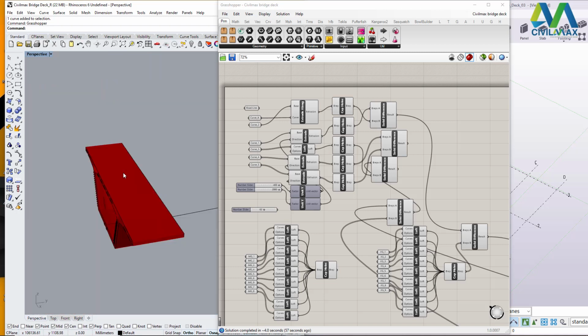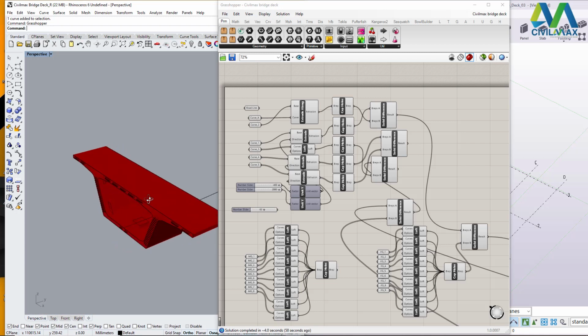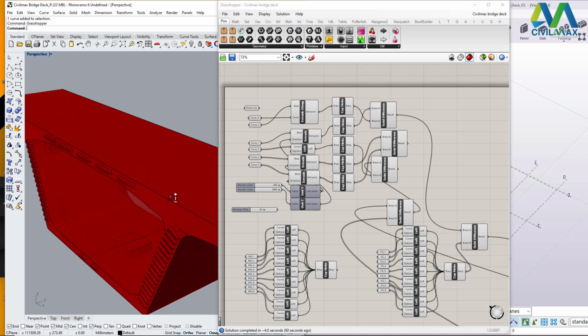And the parametric part that I was talking about is this. Let me bring this close so that you see what I'm talking about. Let me zoom by pressing Control, then pressing the left button and moving your mouse. This will bring it close. This is parametric in this case. This is the full width of our concrete bridge deck. From this end to this end is 2.88 meters.